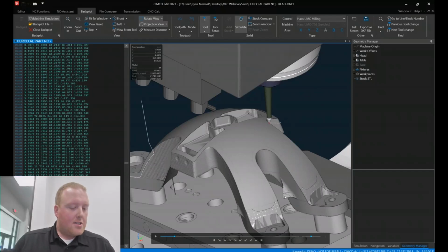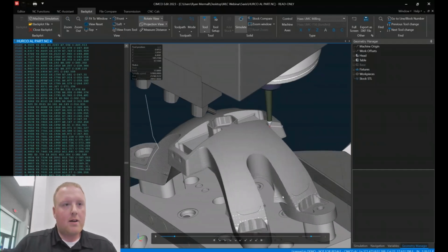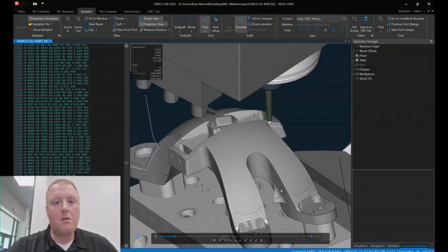Sorry, go ahead. No, I was just going to say, we have something called a reverse post processor. So, as a traditional post processor, Mastercam would generate the code. We obviously have one too that would actually read the code and know how to interpret that as well. So it's all doing all those calculations live, on the fly. Well, and it is moving X, Y, Z, B, and C moves on this UMC 750. So I like that. This is not just some low-powered VF3 solution. It's a full 5-axis simulation.